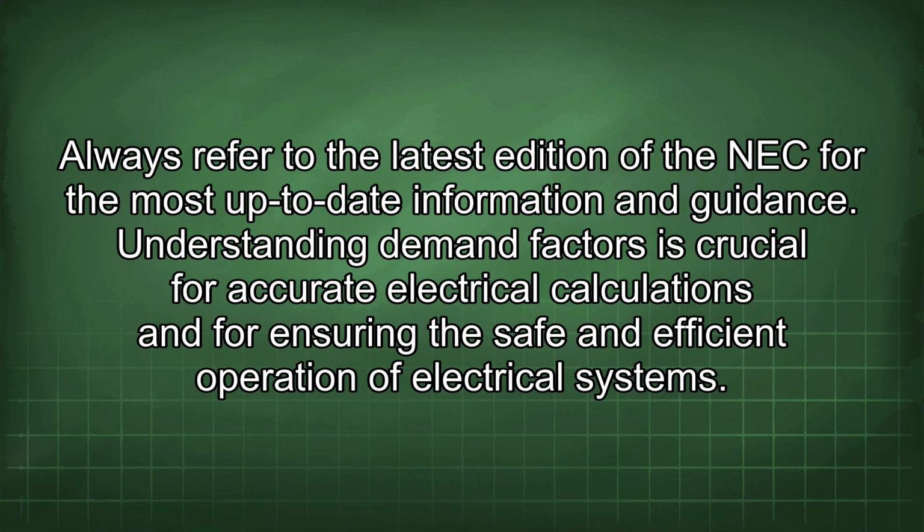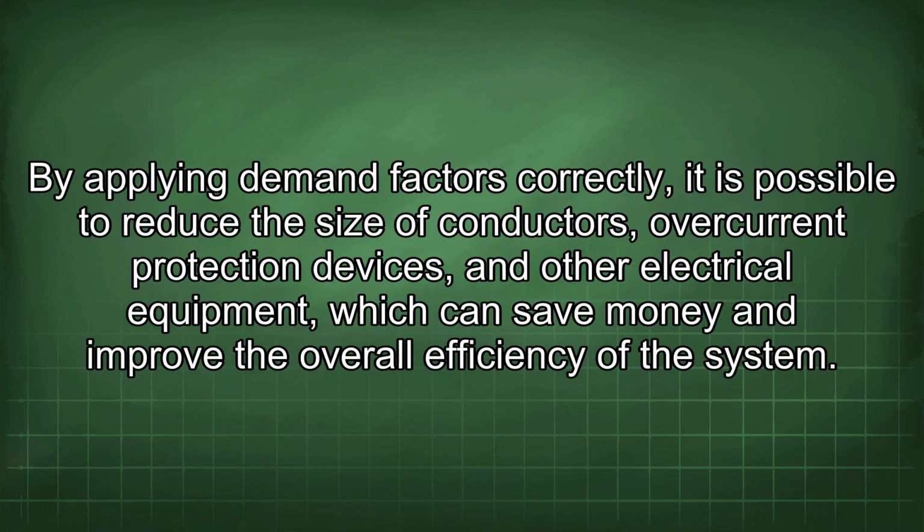Understanding demand factors is crucial for accurate electrical calculations and for ensuring the safe and efficient operation of electrical systems. By applying demand factors correctly, it is possible to reduce the size of conductors, overcurrent protection devices, and other electrical equipment, which can save money and improve the overall efficiency of the system.